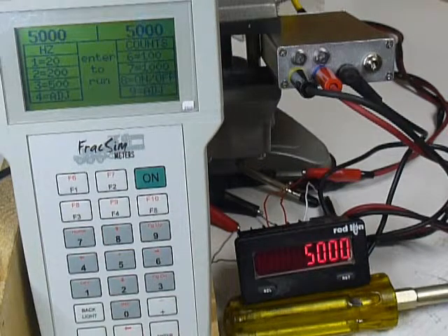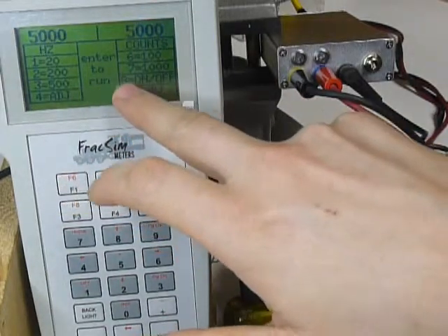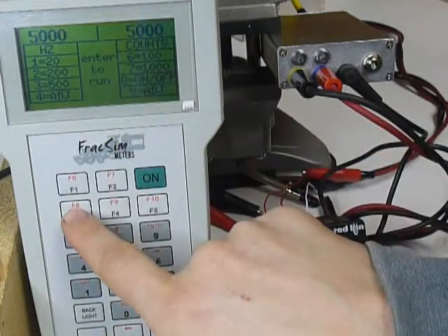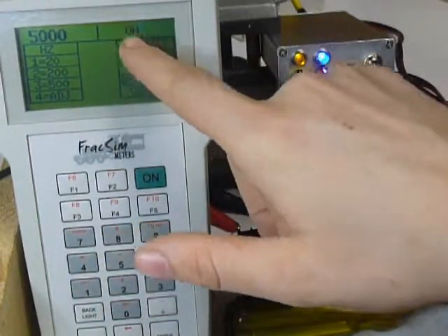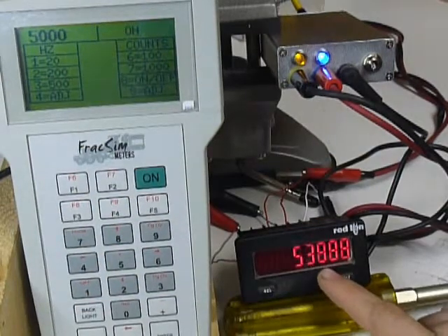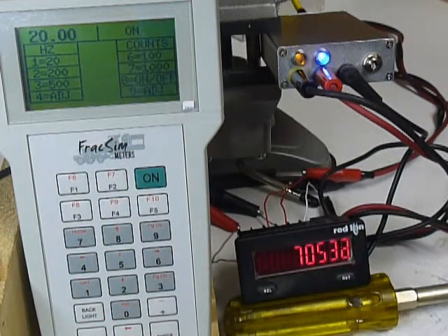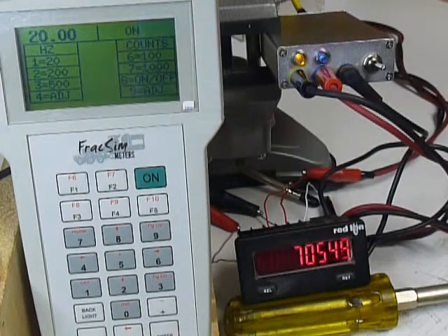Now if you wanted to test something continuously, if you were just troubleshooting and you wanted to find where the issue was, the number of pulses might become a pain if you keep having to restart it. So if you look here, it says number 8 is off on. So what you can actually do is just go Shift F8 and the screen changes to on. You don't see that enter or run anymore, and basically the output is continuously on at whatever hertz you set. So you can see the counter is just going nuts here because we're at 5,000 hertz. We'd slow it down to say 20 hertz. You'll see it slowly incrementing there. And same thing, you can always switch forward or backwards back and forth.